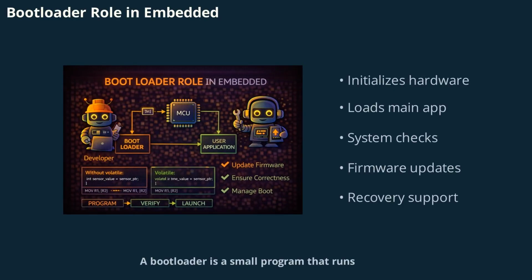A bootloader is a small program that runs before the main application in an embedded system. Its main roles include initializing hardware, loading the main application into memory, performing system checks, and facilitating firmware updates. Bootloaders are essential for systems that require field updates or recovery mechanisms, enhancing reliability and flexibility.